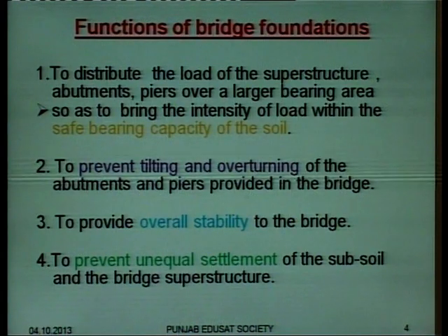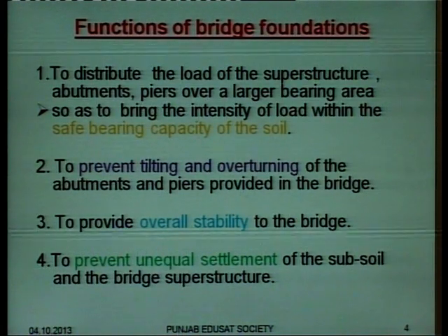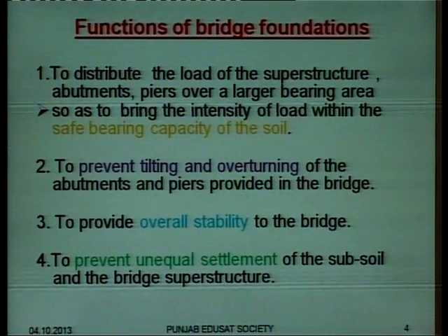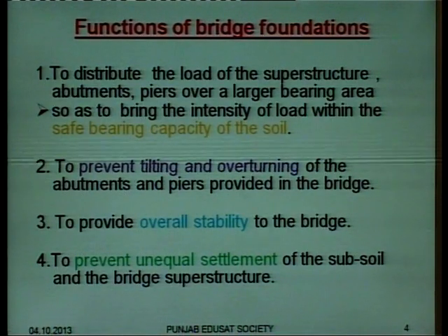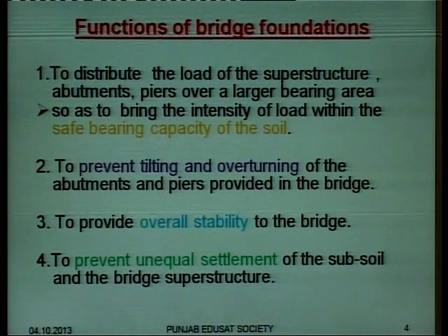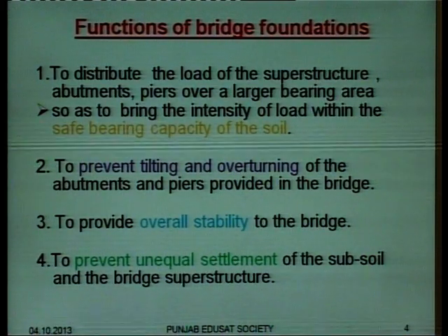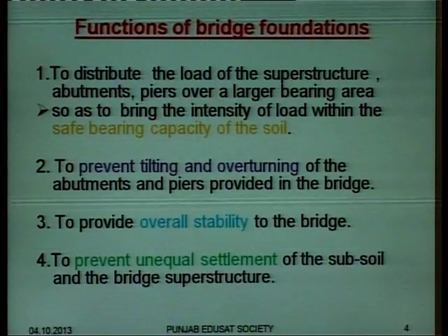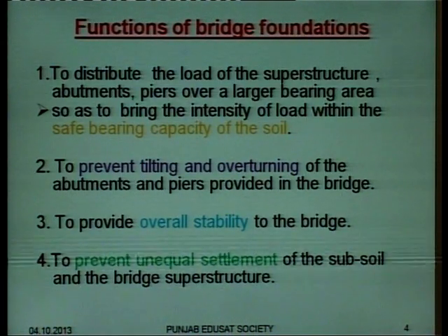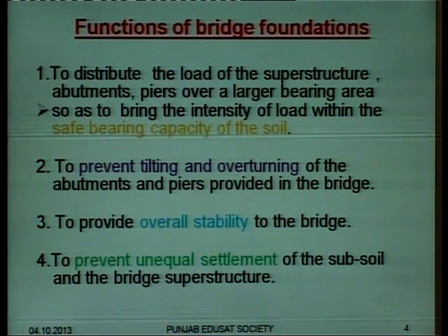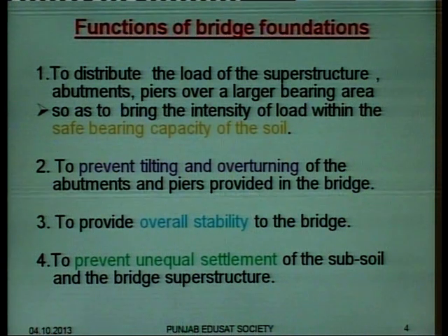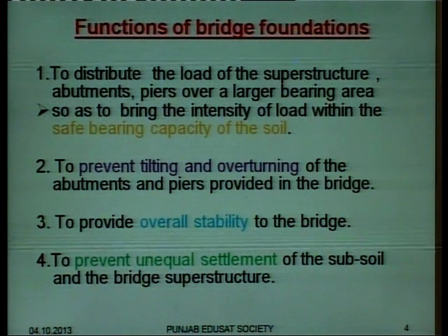The unequal settlement leads to the failure of the structure, and since these bridge foundations distribute the load over a larger area, they prevent this unequal settlement of the subsoil which is beneath the whole bridge and the bridge superstructure.